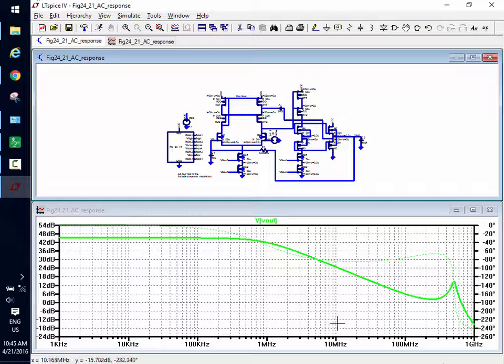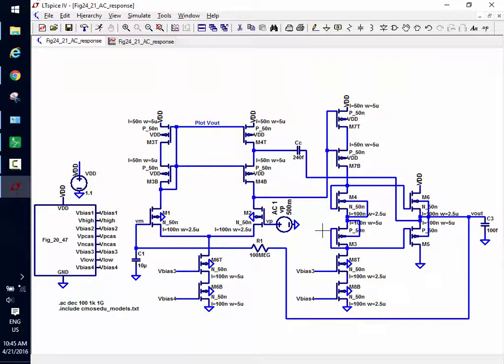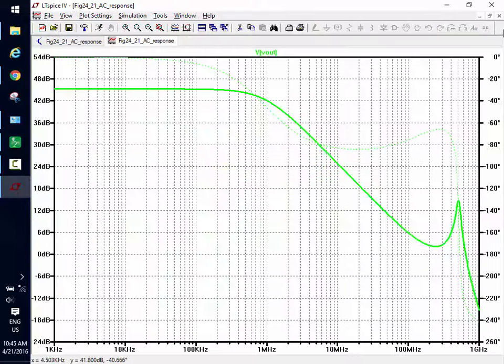So you see the gain go up. The widths on these two are a little bit different on the part you added there. The one is 5U. Yeah, that's the PMOS. The one above it is 2.5U. That's the NMOS. Oh, okay. So you see there's some issues with the DC biasing.